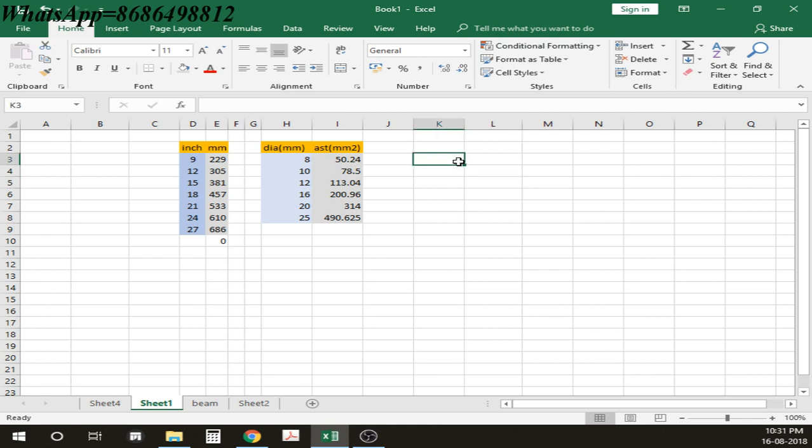So let us think that I'm having a footing of 4 feet by 4 feet, and I'm having its depth as, let us say, 15 inches. Now I'm saying what the units are and what exactly the value is. So I'm saying this is my length, and I'm saying by clicking here that this is in terms of feet. So I'm putting it as FT for the short form of feet. Now the next thing I'm going to do is write here B, and that B is again in terms of feet. So getting back to my bracket, and then I'm writing this as my thickness, that's capital D, and I'm saying this is in terms of inches, INCH.